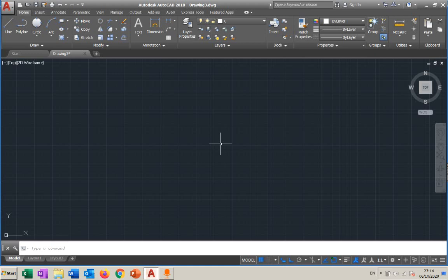In a hand drawing, when someone asks you to draw a plan of a building on paper, you have to make it smaller, yes? Yeah, because the plan of the building, you cannot fit it on an A4 paper or A3 paper. You have to use a scale. Normally they use 1:100 scale, 1:50, 1:25, 1:200.